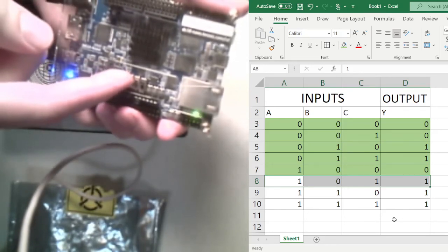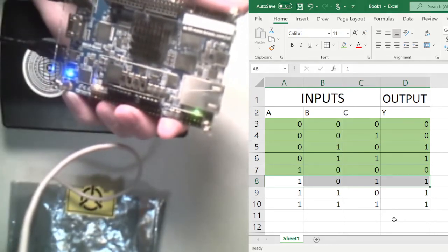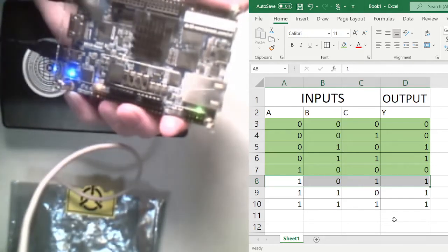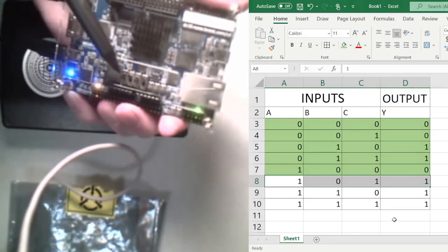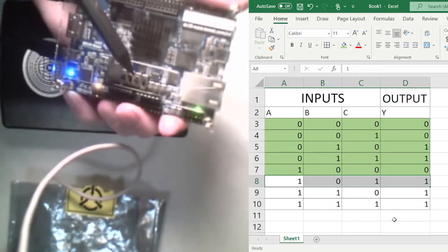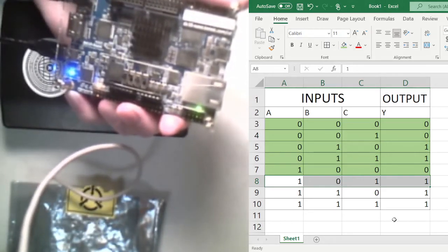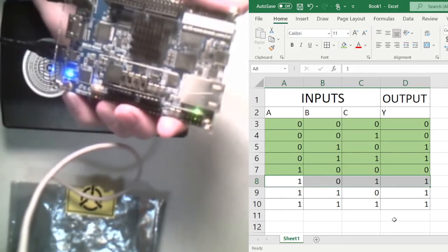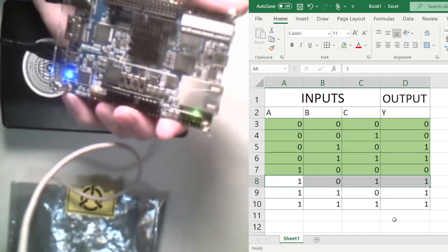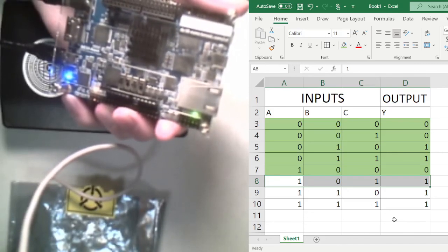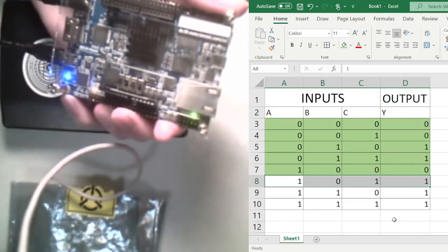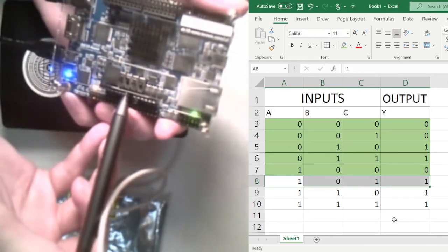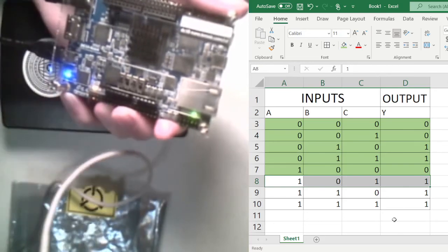Turn on C, it turns on. That is exactly our case right here. So we did not turn on B. The LED does follow B, but we did not turn on B. This is the special case where B is off, but A and C are on. You can see maybe there's some project you're doing where this is a practical thing. You want to always follow this signal except for one particular case where A and C are on. You want to always follow the middle switch, this second switch from the right, except for one special case.